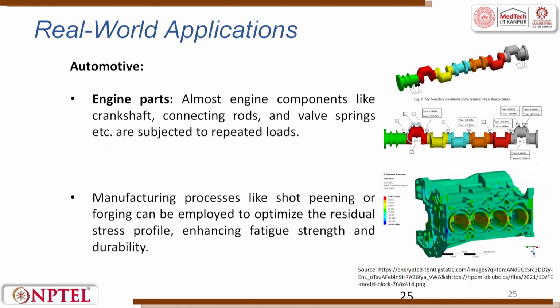So, you see here are some of the major points where there are a lot of stresses which will have an influence. At these regions, they try to introduce shot peening or a special forging process to improve the residual stress.